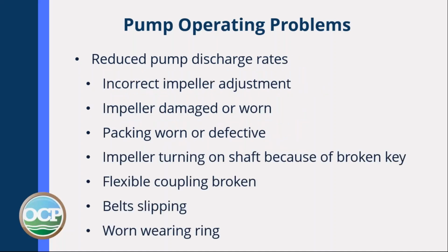Make sure the impeller's adjusted correctly. Check the impeller for damage and see if it's worn. Check to see if your packing is worn or defective. Make sure the impeller is not turning on the shaft because of a broken key. A flexible coupling to the pump could be broken. Belts could be slipping, or your wearing rings could be worn.